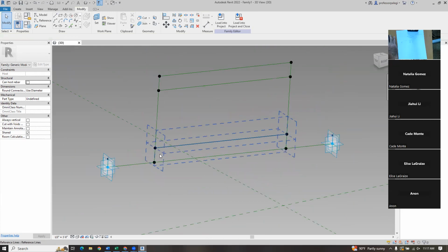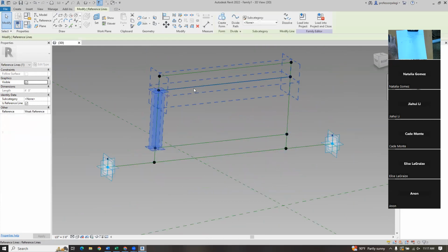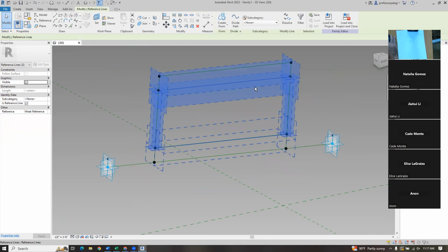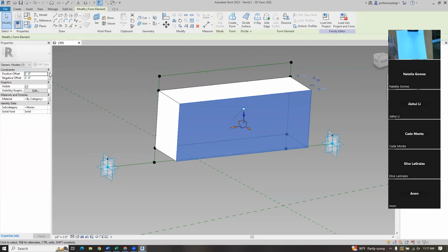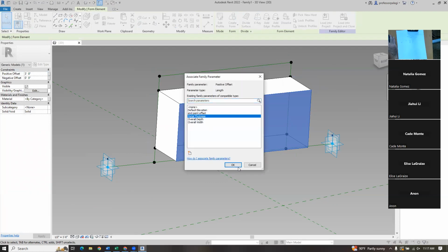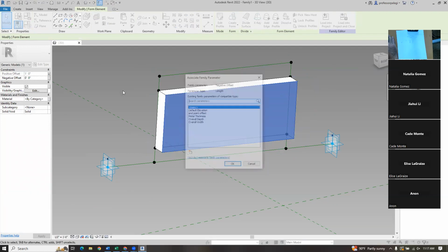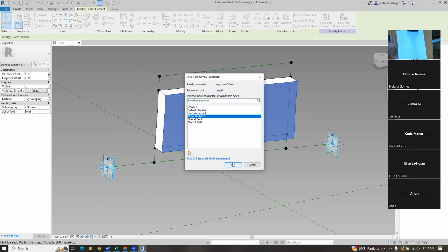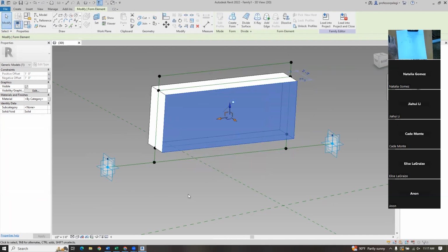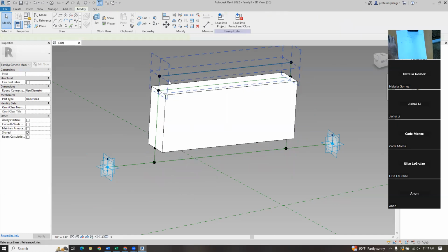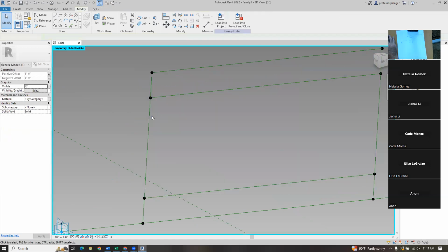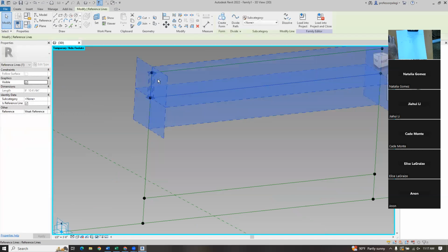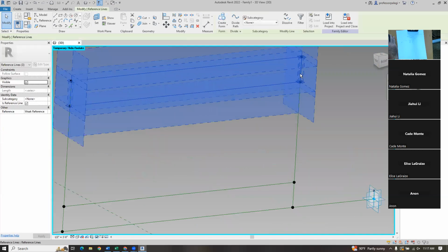You grab them individually. So let's start with the sand because it's the smallest one. I'm grabbing these 3, creating form. I want an object. I want this to be metal thickness, and I want this to be metal thickness. And it's going equal both directions. Right, so center line on there. It's nice and simple. Now we don't have a parameter for this other thing. If I want to make it easy, getting in the habit of just hiding stuff so you can select stuff easy is a good habit when you're working.